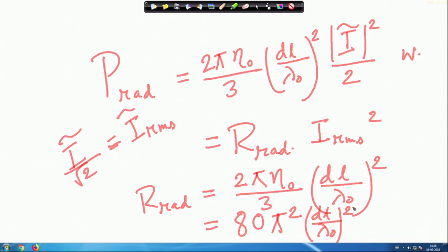Now, what is radiation resistance? If I want more radiation, if I want a more efficient antenna, that means more power. What I am giving is in my hand here, but how much it is sending is given by this. So, more R rad means a more efficient antenna. This R rad is called radiation resistance. Actually, we can say that as if instead of an antenna I have a fictitious resistance, I am giving I RMS current and power is dissipated here.